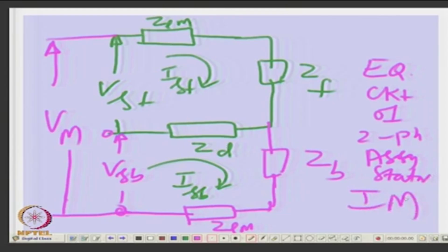Okay. Whatever voltage you apply Vm and Va, so it is a very general equivalent circuit, isn't it? Not particular to any specific case. Okay. And ZD is important, ZD is half of ZLA dash minus Zm. But if it is a symmetrical machine, what will happen?